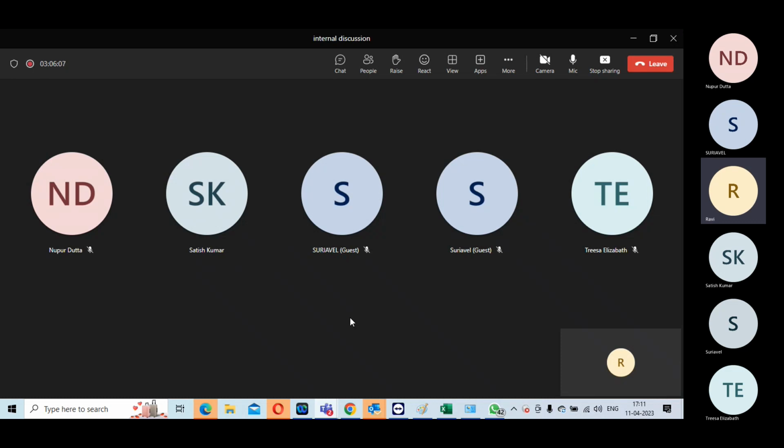Clock buffers can drive more length. For levels of logic, clock buffers are always preferred because a clock buffer will be able to drive more length. Because it's able to drive more length, the number of switching will reduce. For power point of view, clock buffer. For transition, timing, insertion, clock inverters. Because the more the number of switching, the more the power consumption, right? Dynamic power consumption.